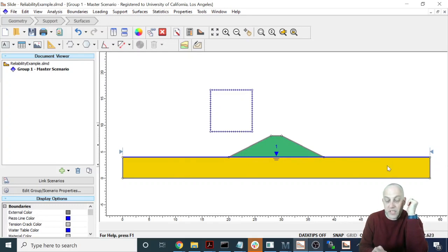Maybe it would be a function of depth, but it would not be a function of horizontal position, because at the time you've constructed the levee, no consolidation has happened yet. It's undrained, it hasn't started settling and getting stronger. If you build one stage, let's say, this is 4 meters high. Let's say you build 1 meter first. Well, now maybe you're going to have a higher shear strength under this region before you add the next stage, because you've waited for consolidation to happen after stage 1 and before stage 2.